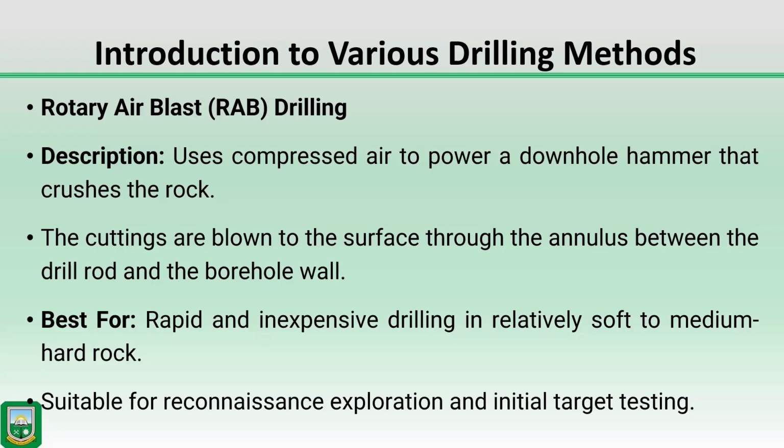So we have a down the hole hammer, and the down the hole hammer receives its energy or its power from the compressed air, which pushes the drill bit into the formation and crushes the rock, penetrating into it. So that's the peculiarity about air blast drilling.